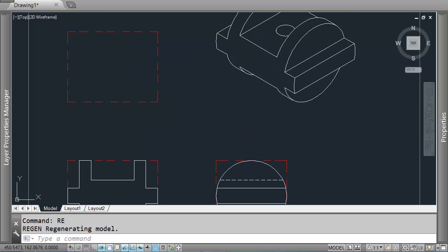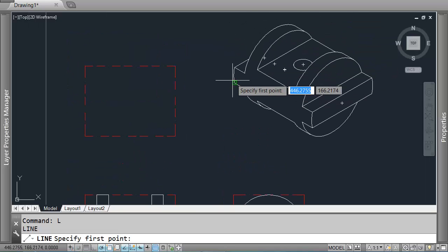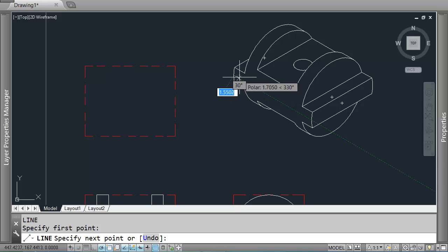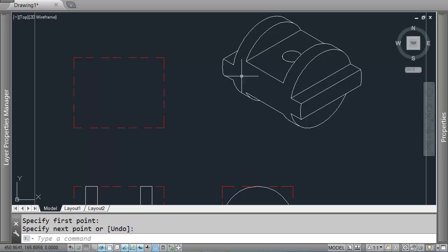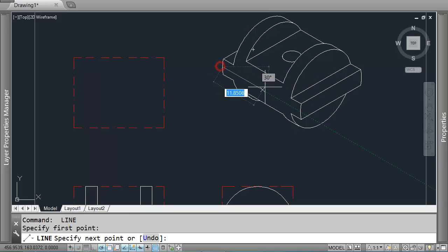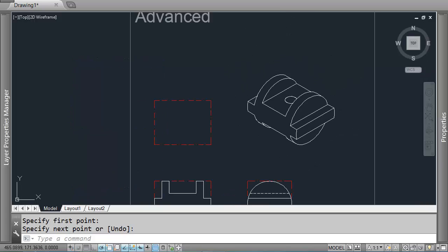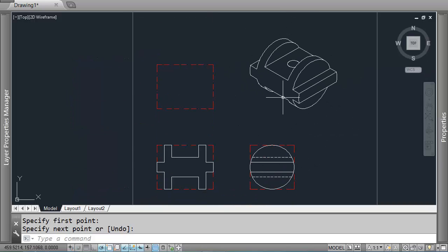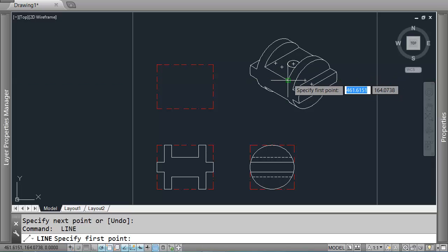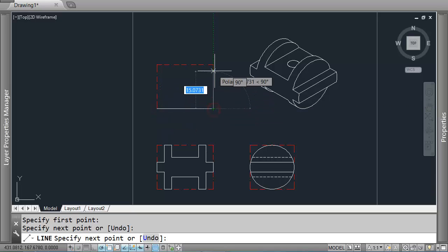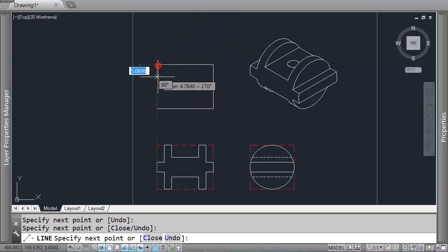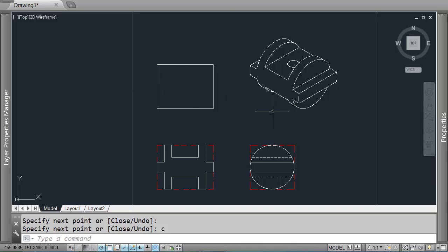Because this object, as we can see in isometric, has an edge which runs the entire length of the shape, which is part of the outside of the cylinder. If that cylinder is touching the outside edge, then when we view the object from the top down, it's going to be seen as a rectangular object, and we would need to fill in some of the other detail that will tell us that a circularity is present there. But from the top down, the entire cylinder will appear rectangular like that.